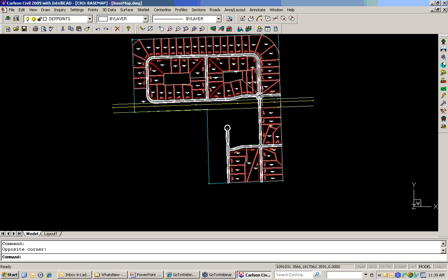And then it would just be a matter of freezing particular layers. And for profiles through the end of the cul-de-sac, we might have to defer on that one a little bit. We would have to basically go through and tack in some additional profile data into the profile for this center line. So these can be done. They're going to go beyond the scope of today's presentation, but you can certainly work with that going through your project designs.